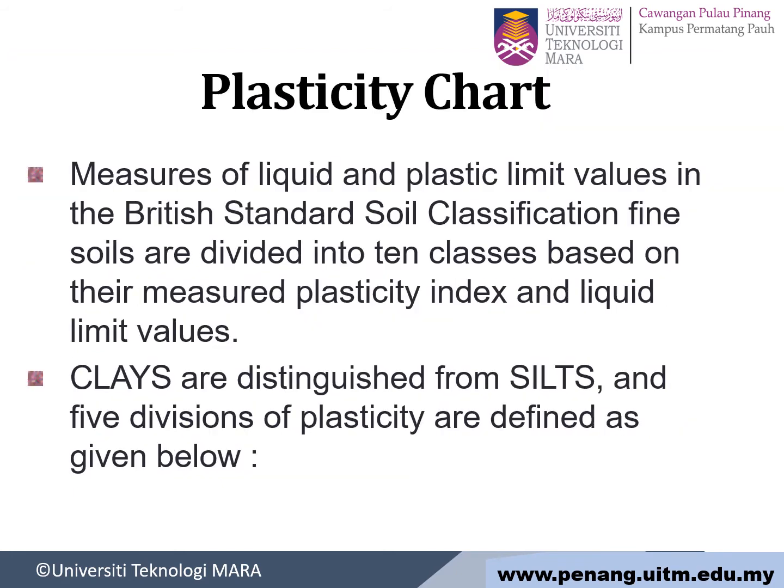Plasticity chart. Measure of liquid and plastic limit value in the British Standard Soil Classification System. Fine soil are divided into 10 classes based on their major plasticity index and liquid limit values. Clay are distinguished from silt, and 5 divisions of plasticity are defined as given below.